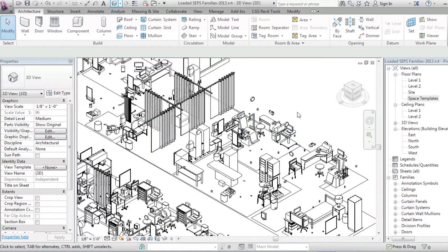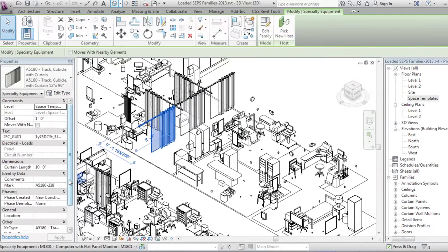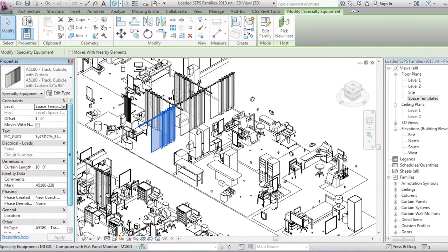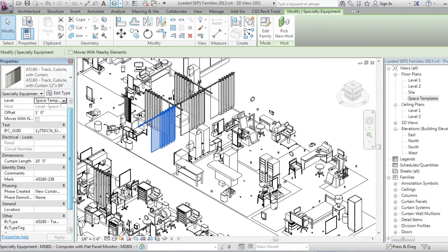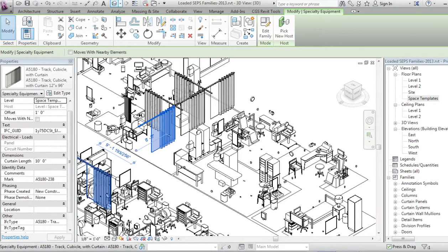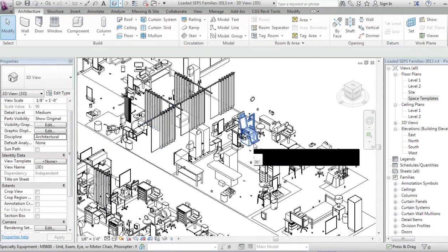So in Onuma, when we saw these objects, they were blocks, but they were actually tagged to the correct object in Revit. That's why when we export from Onuma into Revit, it goes and grabs the right family object, not only the object, but the actual attributes related to it. So if the attributes were associated with the object, on the left side you see the actual attributes about the mark number, for example, and the IFC GUID that came from the model that started in the Onuma system.